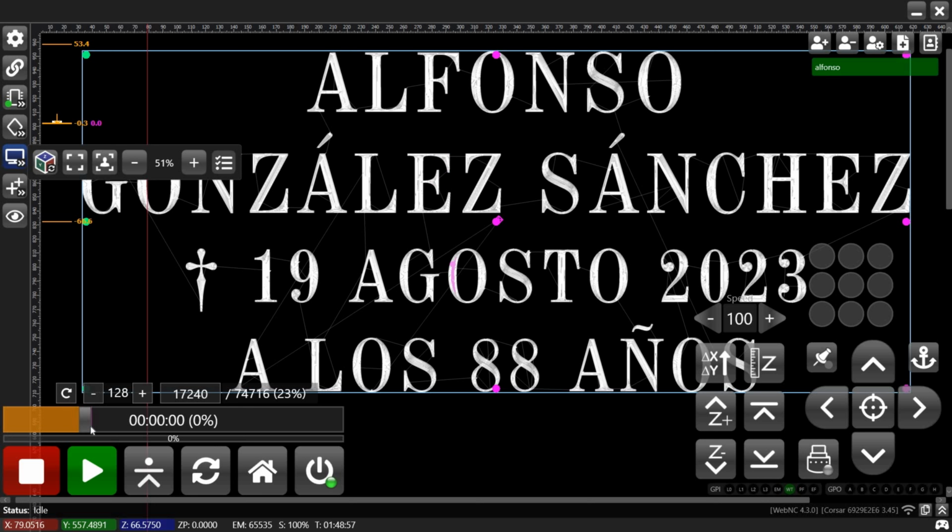This option is particularly useful in case the cutter breaks during the operation, while the machine keeps running. So we'll need to go back to where it broke down. Thanks to this option, little experience is needed for an operator to resume and complete the job without any artifacts or signs of failure. This button forces the machine to resume work from step 0.